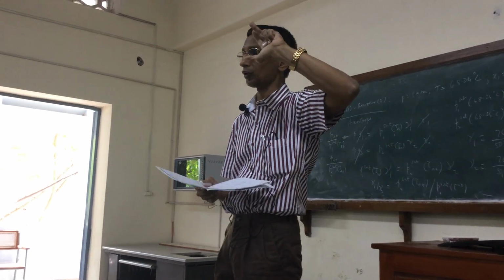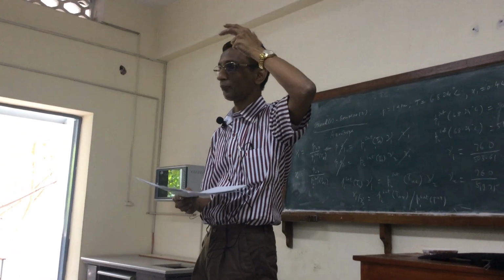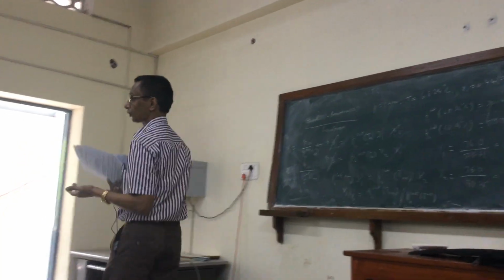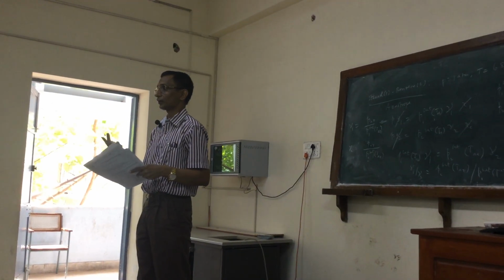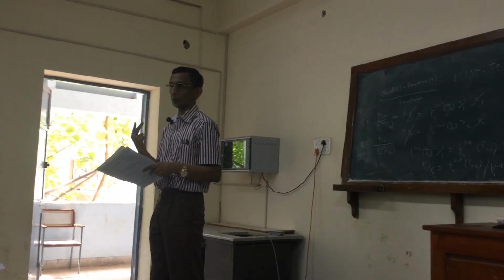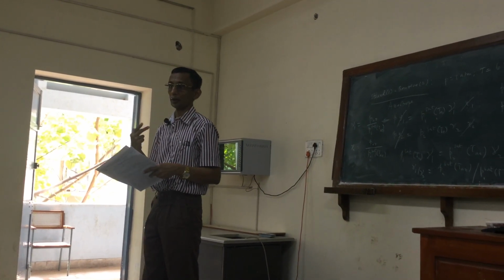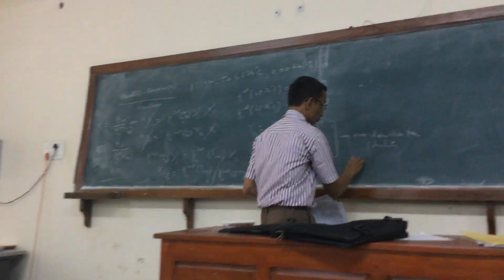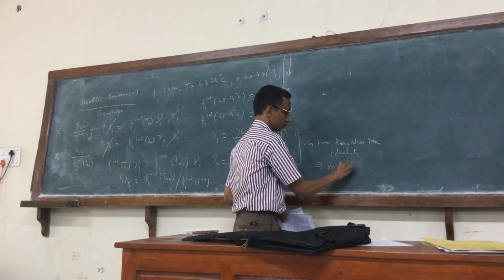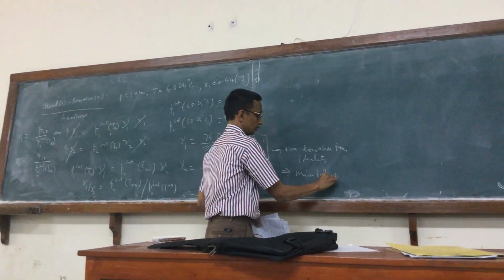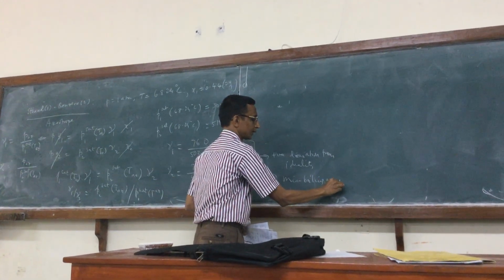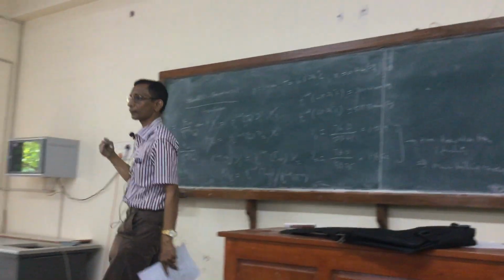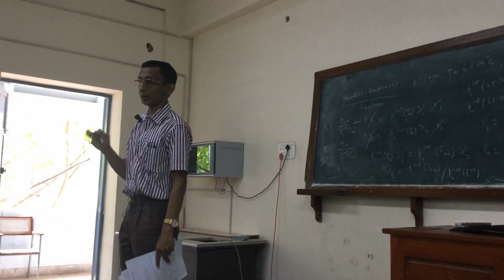The calculations you don't need to know, but constructing the phase diagram is useful to know whether this is going to exhibit a minimum boiling or a maximum boiling, just by looking at the values of gamma. Positive deviation, minimum boiling azeotrope. You should also know what minimum boiling means. Minimum boiling means that at the given pressure, if I plot the Txy diagram, because that's very important.